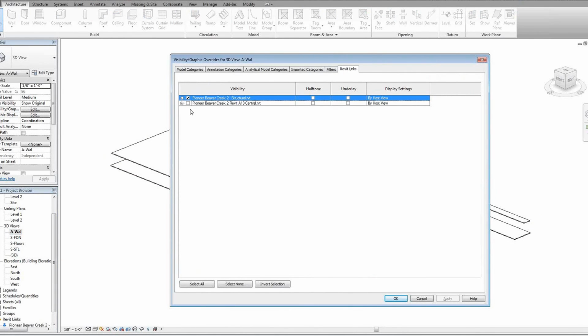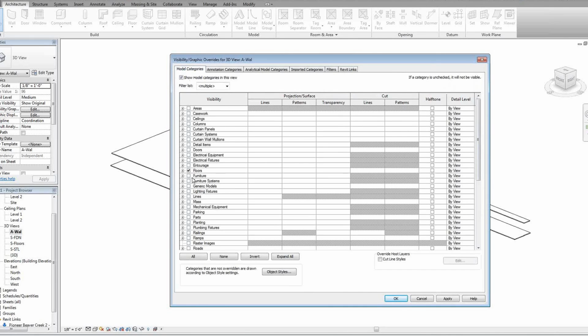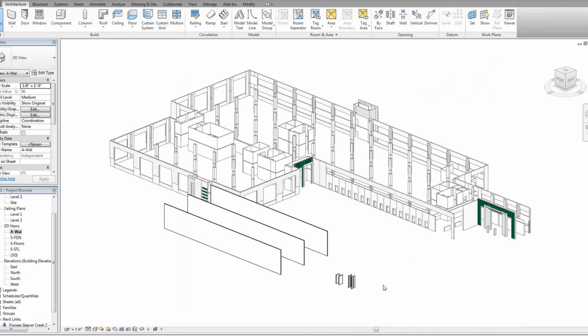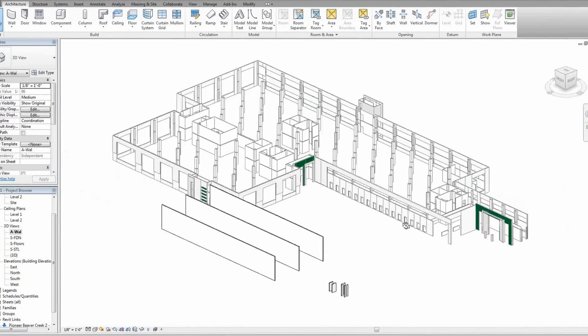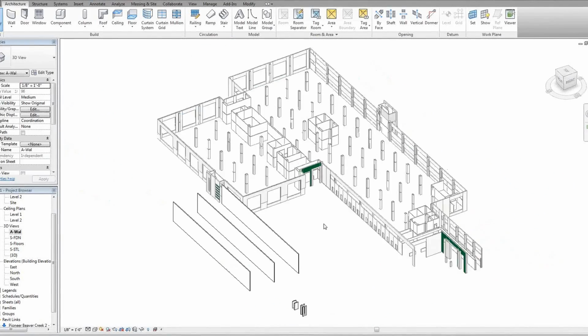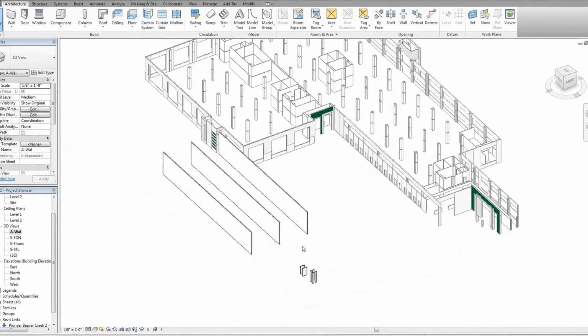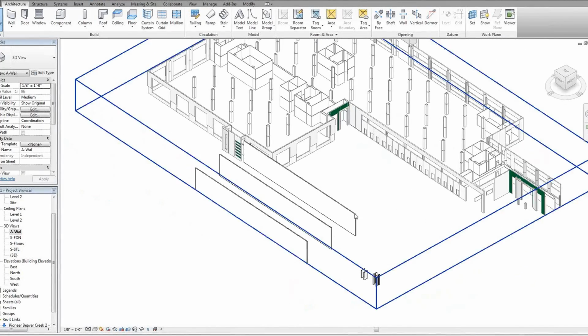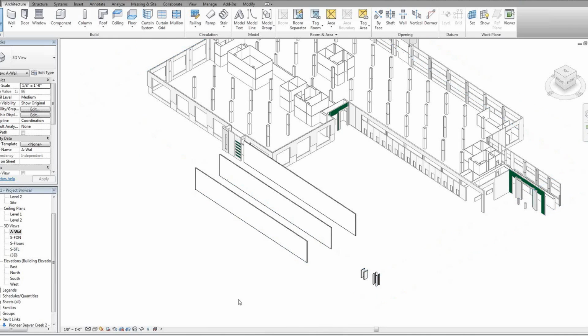So I have to turn on the architect's model. I'll turn off the structural engineers, turn off floors, and turn on walls. So now this should be architectural walls. So we've got a little bit of space junk out here. These guys out here probably aren't just something they were modeling off in space to then reuse. So we want to turn that off because we want clean exports for everyone to use.